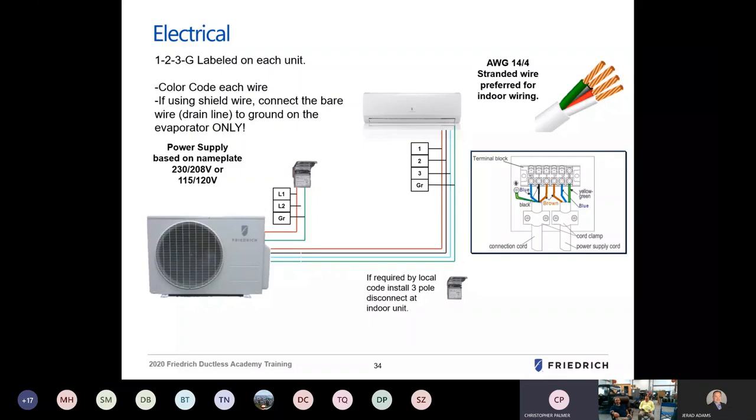You may have a yellow with a stripe, but make sure that you correspond the proper terminals with the proper landing spots of the other wire. Oftentimes, you'll install a unit, you'll power it up, and you won't get any response from the equipment. There's a good chance that your landing spots for your wires are incorrect. I would go back to that and start fresh and look over your wiring connections and make sure everything is